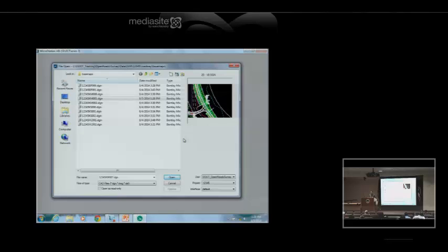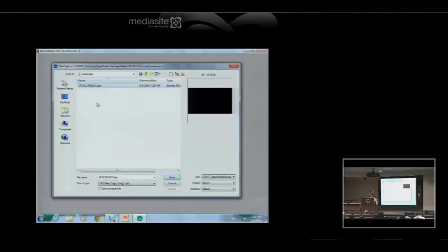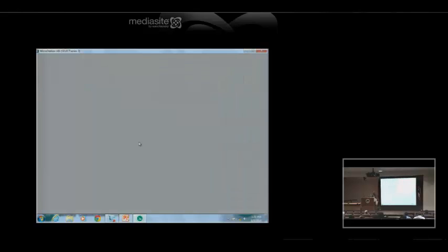I'm going to go to this project 80127, which was in Lorain County, and under survey base maps, I have an empty file created. The survey training data set that we've got for the OpenRoads survey class has these files already laid out. Most of them, I think, are already laid out. You don't actually create the files. And we'll wait for that to open.